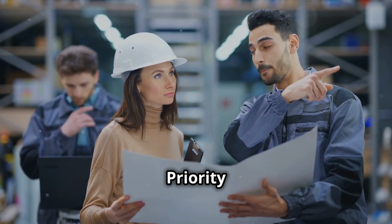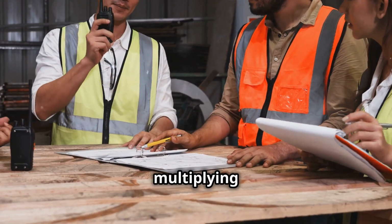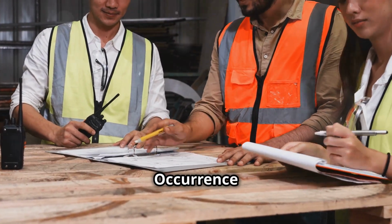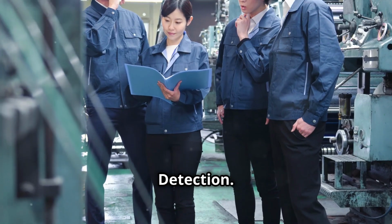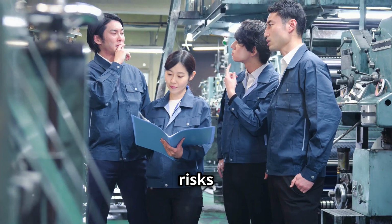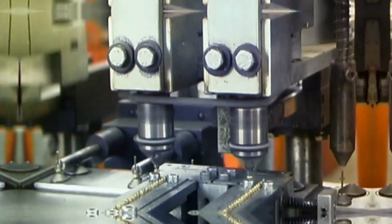Finally, risk priority number, or RPN, is calculated by multiplying severity by occurrence by detection. Higher RPN values indicate higher risks and guide prioritization for action.